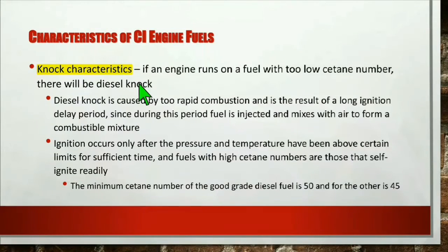NOx characteristics. If an engine runs on a fuel with too low Cetane number, there will be diesel knock. Diesel knock is caused by too rapid combustion and is the result of a long ignition delay period, since during this period, fuel is injected and mixes with air to form a combustible mixture. Ignition occurs only after the pressure and temperature have been above certain limits for sufficient time, and fuels with high Cetane numbers are those that self-ignite readily. The minimum Cetane number of the good grade diesel fuel is 50 and for the other is 45.